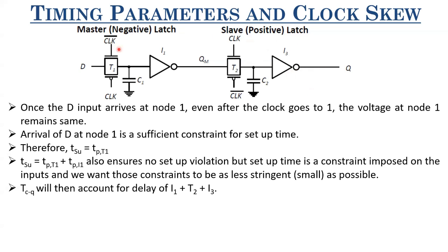So the delay remains the same regardless of what you are taking as setup or TCQ. It's just how you are dividing this, so that the correct operation is also ensured, and you are putting less constraint on your inputs. So let me repeat it again.